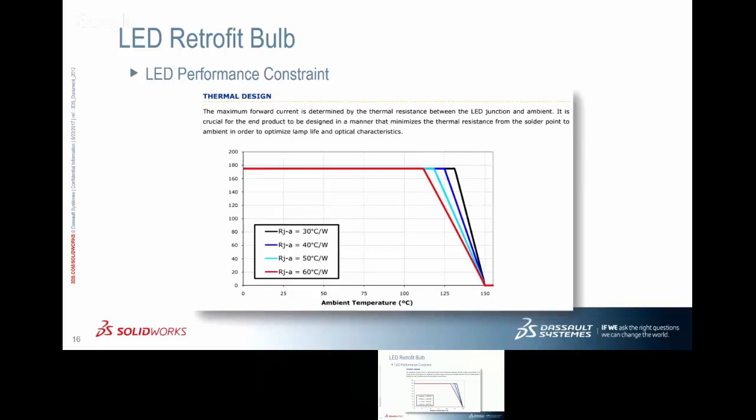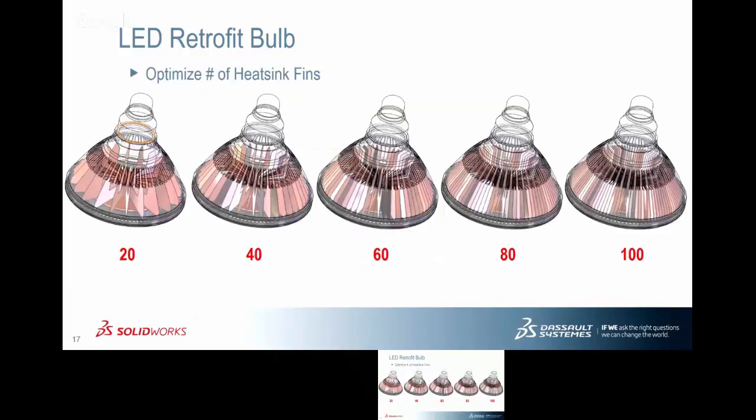So it's really critical in your design that it does not get too hot. When you're designing a form factor like this and you understand the environment, we know that specifically with LEDs, they need to stay within a very specific temperature range for them to hit their 50,000 hours and to make sure that the color temperature is accurate.